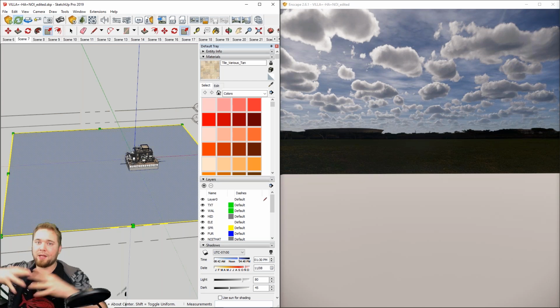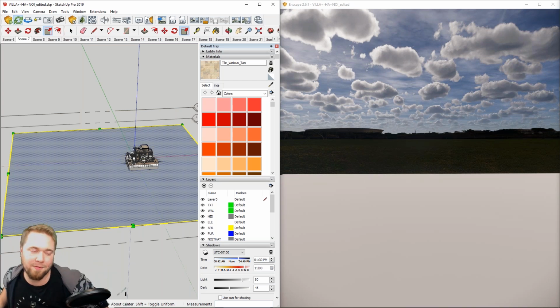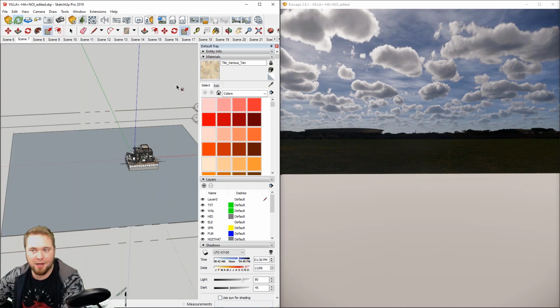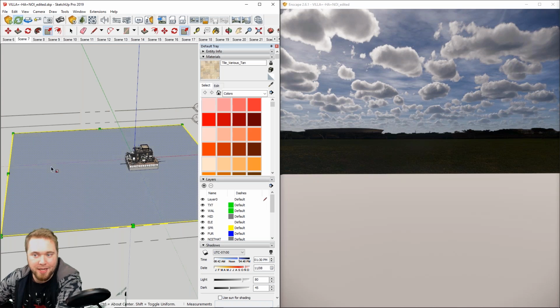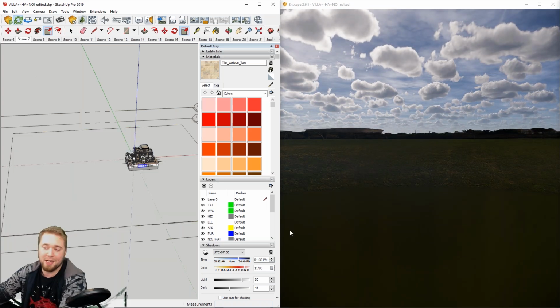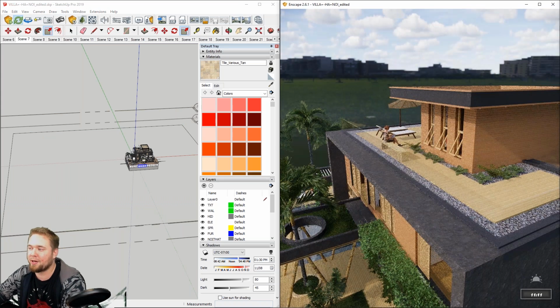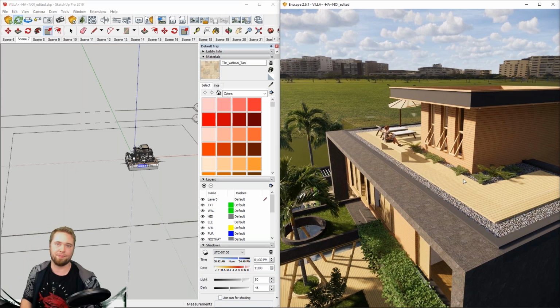But really, really large faces and objects in Enscape are a little bit problematic in any case, because Enscape is calculating the shadows for the whole scenery at once, and it takes the size of your project into account.